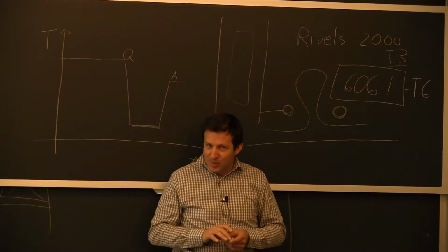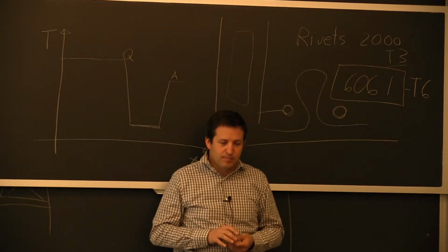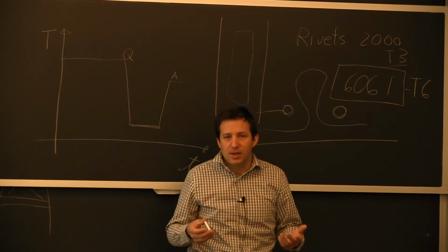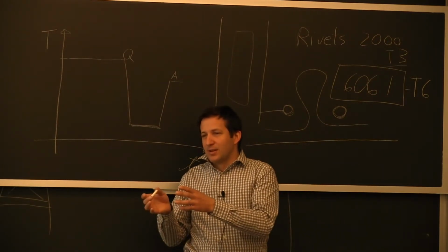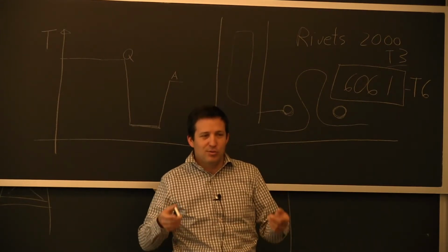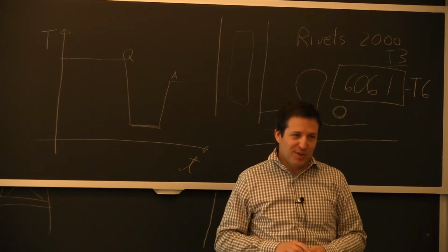It's very limited. And that's where this load resistant factor design concept comes in. The more you know your load, the more you know your resistance, you can reduce the difference between them. So instead of being 2, 3, 4, 5, or 10, it becomes just 15%.